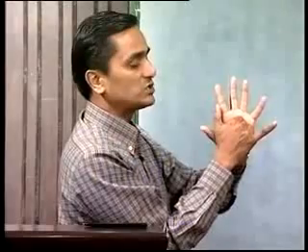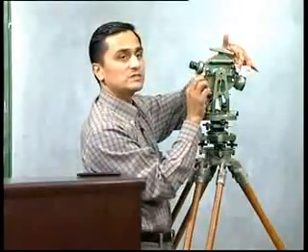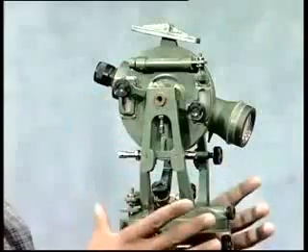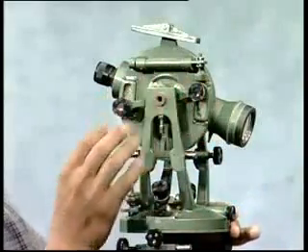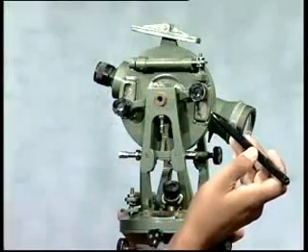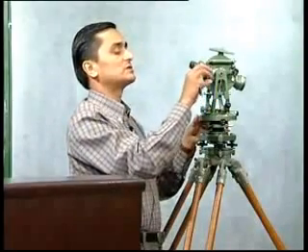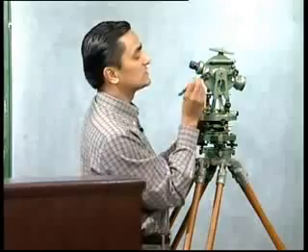Initially, let us say the reading was 0, 0. My telescope is horizontal, like this, and the reading is 0, 0. Now I rotate my telescope, so my vertical circle will rotate. The angle between these two will be the vertical angle. By rotating this, we can see it again using these eyepieces. We could not see those windows in case of the horizontal circle, but we can see the windows very well in case of the vertical circle. This is the window for vernier A, this is the window for vernier B. By making use of these windows and these eyepieces, I can focus this eyepiece to my eye, and we can see the readings through this.